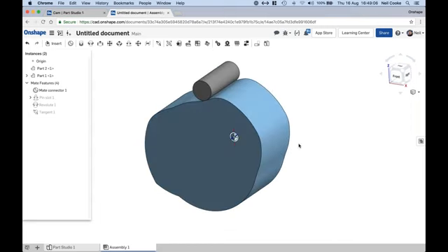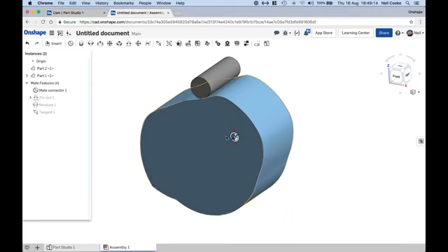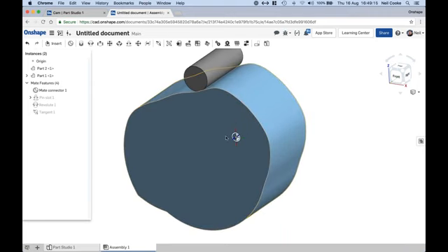Okay, so that's essentially what I wanted to cover today. I do apologise at the start when I made a little bit of a mess of that sketch, lack of practice. But essentially, building either a sketch layout to drive your linkages and making use of the equal constraint is the way forward. Unique to Onshape is using the in-context editing, which means that you can position complex assemblies in multiple locations to work out linkages.